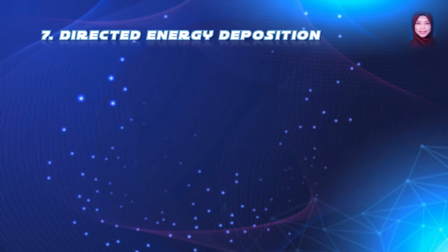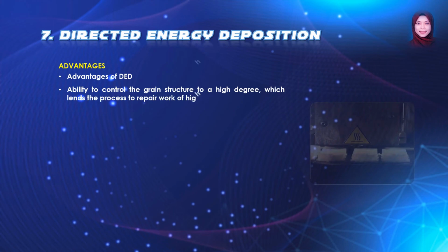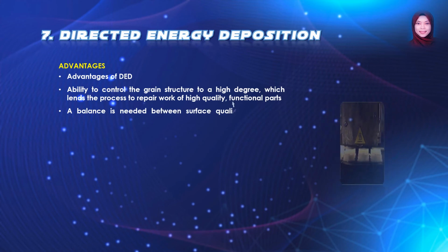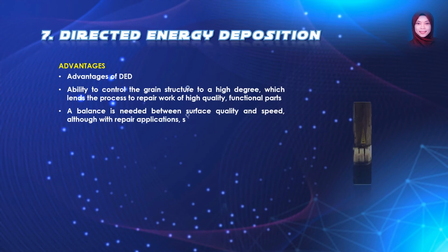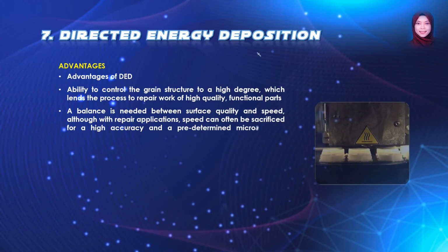Directed energy deposition. Advantages of DED: ability to control the grain structure to a high degree, which lends the process to repair work of high quality functional parts. A balance is needed between surface quality and speed, although with repair applications, speed can often be sacrificed for a high accuracy and a predetermined microstructure.